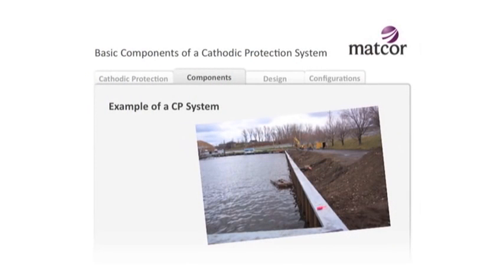So if you've got a LNG terminal where you're going to bring in large LNG tankers, you know, you're not going to just run those up to the shore and have them hit the sand. You've got to create a channel, a deep channel, where you can berth the LNG tanker. Seawalls are very common to do that. So what you see here is a typical seawall. And if you can see it closely, you can see there's a little bit of rust on the atmospheric side of the seawall. Okay? Rust is an interesting thing because for certain steel structures, rust becomes a coating, and it kind of slows down the corrosion after that.